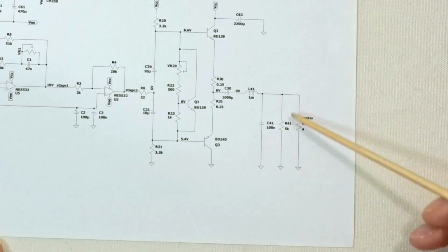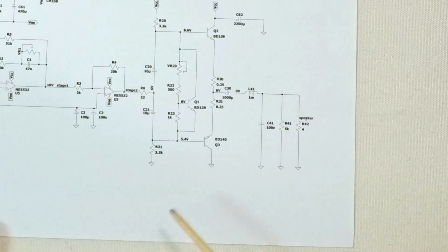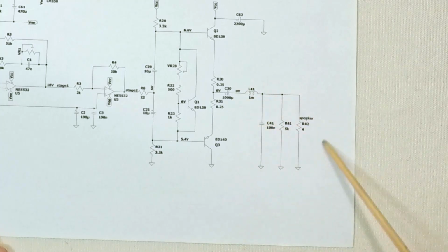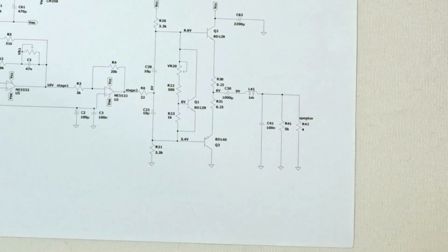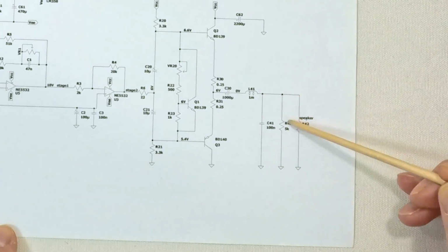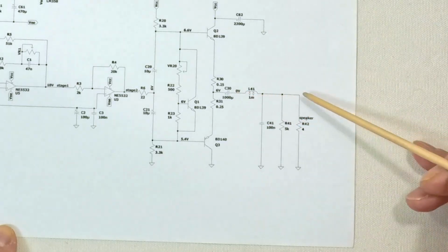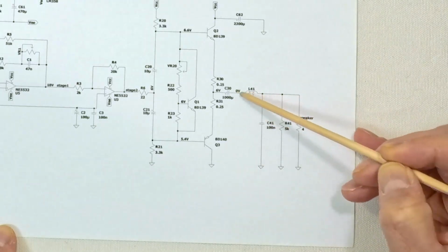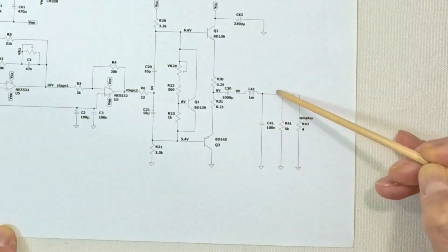I've also put in the option for a discharge resistor here. On startup, a voltage can be induced in this part of the circuit through the capacitor. Speakers are not built for DC voltages, so by putting in a discharge resistor, it can help to get rid of the voltage. But in my case, with these low voltages, I don't know if that's necessary.